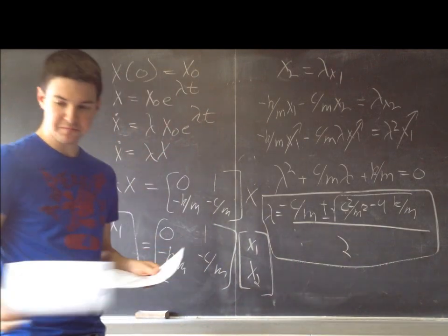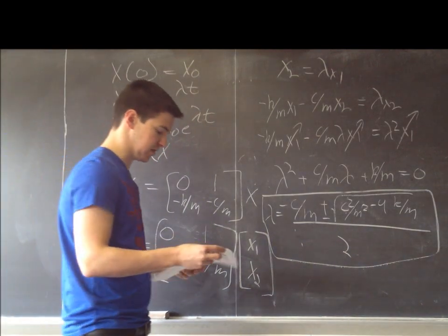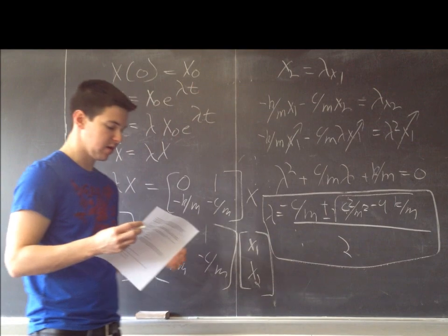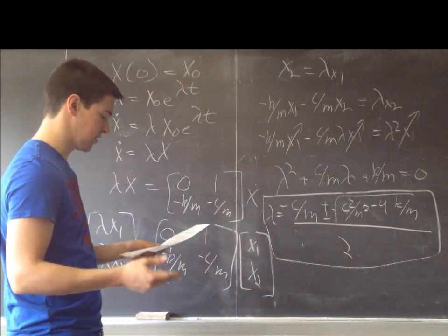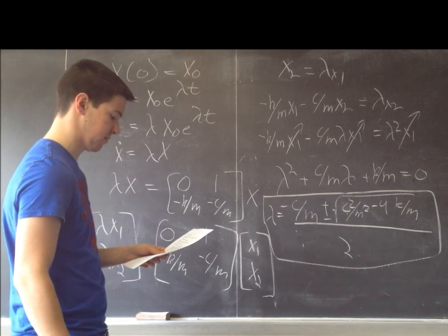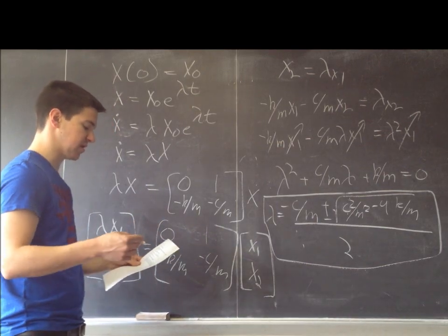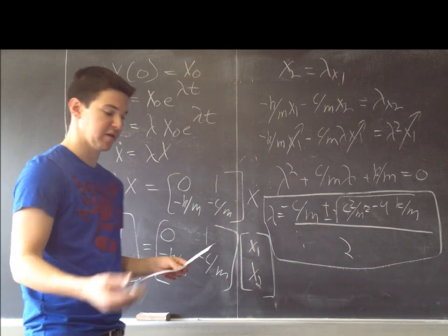So that's about it. The result of this problem is that given an initial condition, we are able to mathematically represent the free response of the mass spring damper system. In this case, the system will operate at some frequency that is paired with a decreasing sinusoidal function.